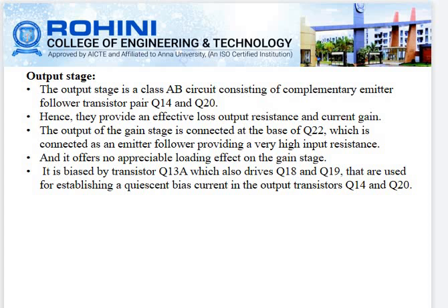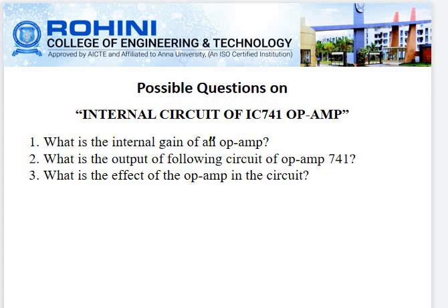It is biased by transistor Q13A, which also drives Q18 and Q19 that are used for establishing a quiescent bias current in the output transistors Q14 and Q20.